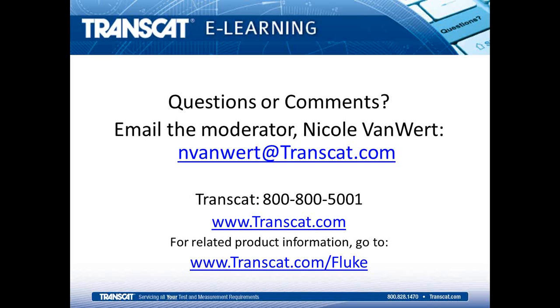So what if the probe is 1 inch long? Would this work in a dry block or would a bath be preferred? Yeah, something that short we would definitely prefer to do in a bath. The diameter of that probe could also cause some problems. If it's really small in diameter, that would be helpful. But the challenge is, you need to try to put a reference probe at the same depth if you can, and likely 1 inch is going to have a huge impact on a reference probe. So it's kind of a bad scenario.